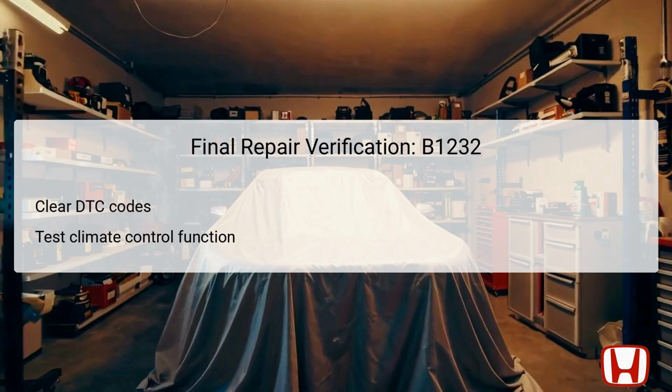During this phase, the technician should monitor the operation closely to confirm that the evaporator temperature sensor accurately communicates with the climate control unit and that the cabin temperature regulation is optimal. Successful verification is key to ensuring that the initial problem has been addressed and the vehicle operates properly without recurrence of the DTC.